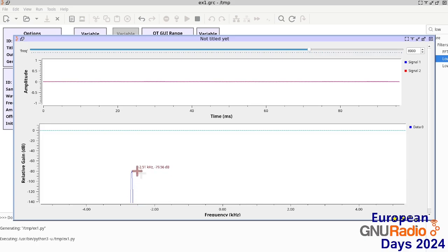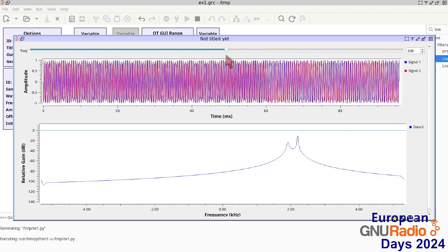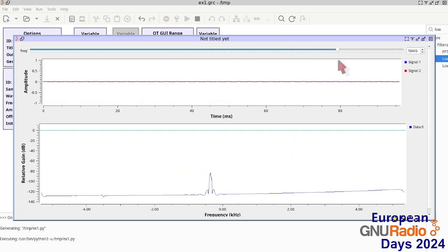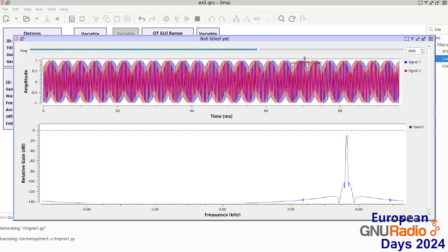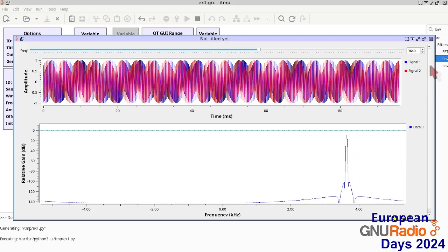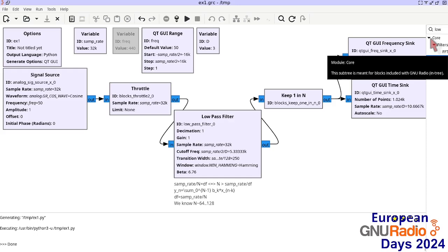-78, 79 dB. So the signal dropped by 70 dB between, and the time domain is hardly visible here, between baseband and the second Nyquist zone. So we've effectively removed aliasing effect because by low-pass filtering we've removed all the unwanted spectral characteristics.